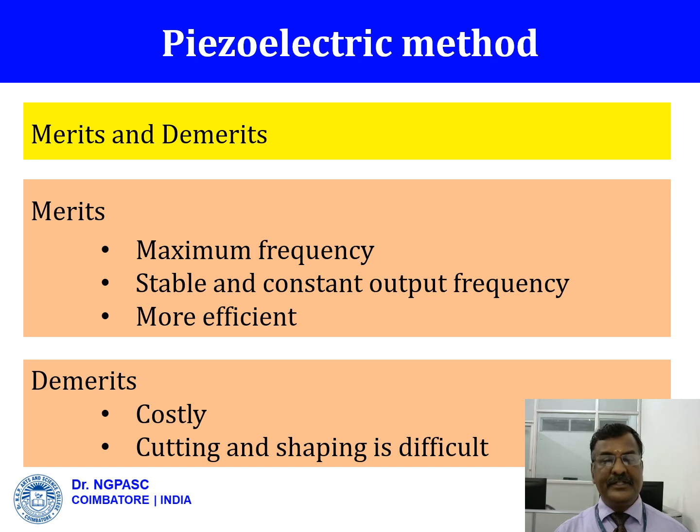In the demerits, since crystals are used in the production of ultrasonic waves, the crystals are costly. Before using the crystal in the circuit, we have to cut and shape the crystal in an appropriate manner. Cutting and shaping the crystal is a tedious and difficult task. These are the demerits of the piezoelectric method.